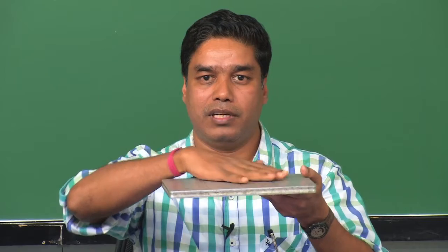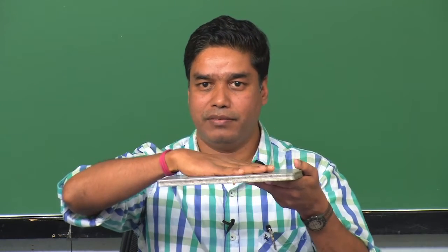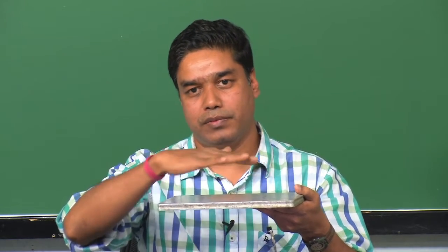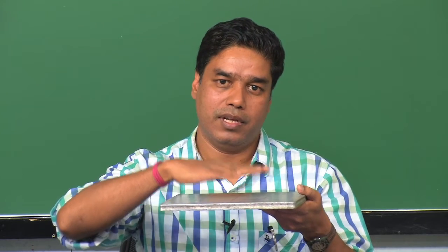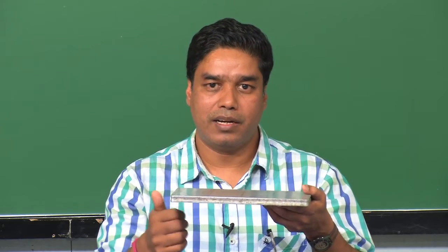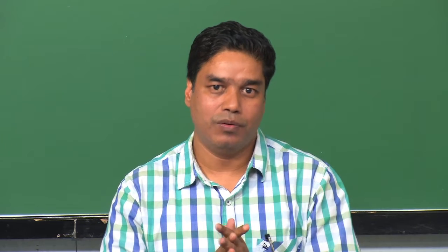Then the sample is kept on the top surface. Right below this you have the intensifying screen and then you have the sample. If you remember, we also discussed that the intensifying screen has to be in between the sample and the film, and it should also be there on the bottom surface, so that the backscattered radiation can be addressed. So, this is one aspect of exposure: how to load the film for a particular exposure.